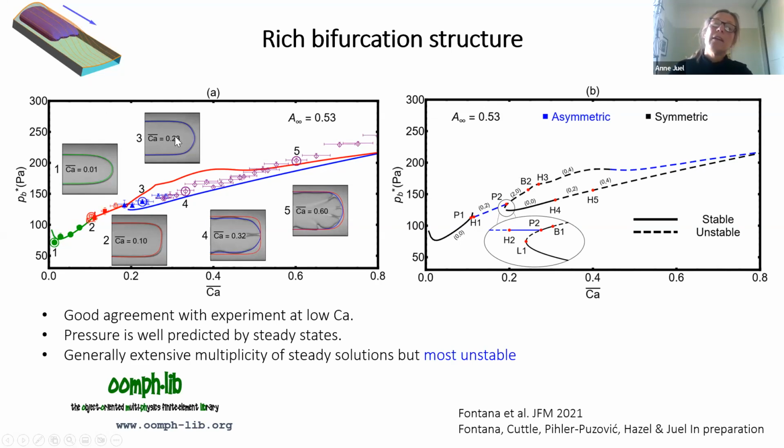These are taken into account in a slightly ad hoc but fairly successful manner, based on what can be calculated in rigid channels. We essentially adjust the mass conservation in the system by imposing these passive layers of thin films that have a particular dependence on capillary number. And when you do that, then you get the right finger width and all the rest of it.